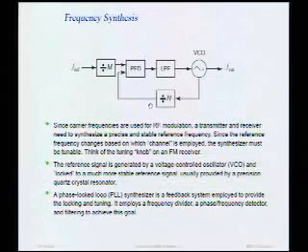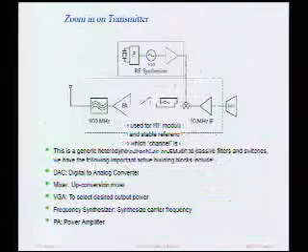I assume you know how to build a low-pass filter. But we'll talk about how you stabilize this feedback system. It's actually a tricky feedback system because it involves a lot of nonlinear components. And we'll find that we can linearize this system over a small range and analyze it as if it were a linear circuit. So we'll talk about that also later.